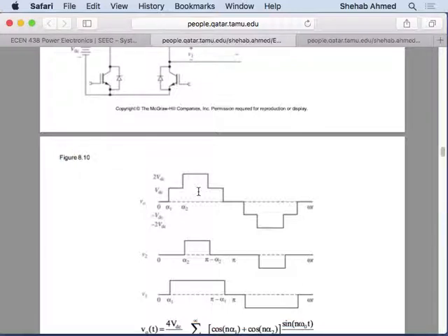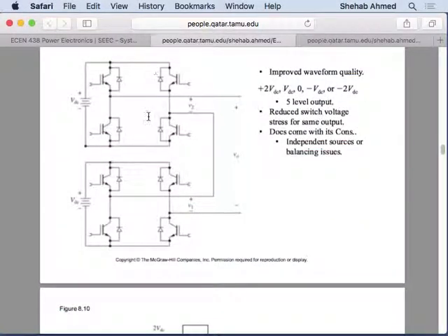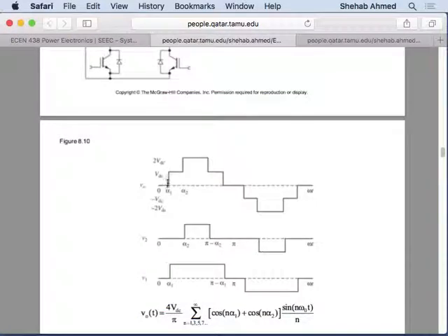So we had initially a single pulse with some zeros. Then multiple pulses: single value, 0, single value, 0, single value, 0. It gave us something. But now there are other converter topologies, multi-level inverters, for example, that can give us multiple values, multiple levels. How about if I have these multiple levels and add as well this value and 0, this value and 0, this top value and 0? Then I have even better control, right?